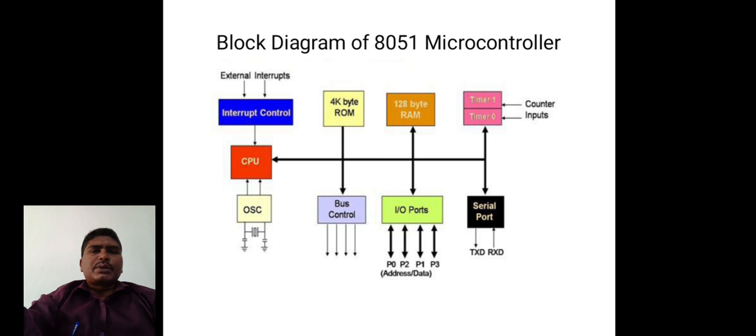Here we are using ROM and RAM. Suppose we want to interface external memory to the 8051, we need this bus control, which provides the data and address bus lines.